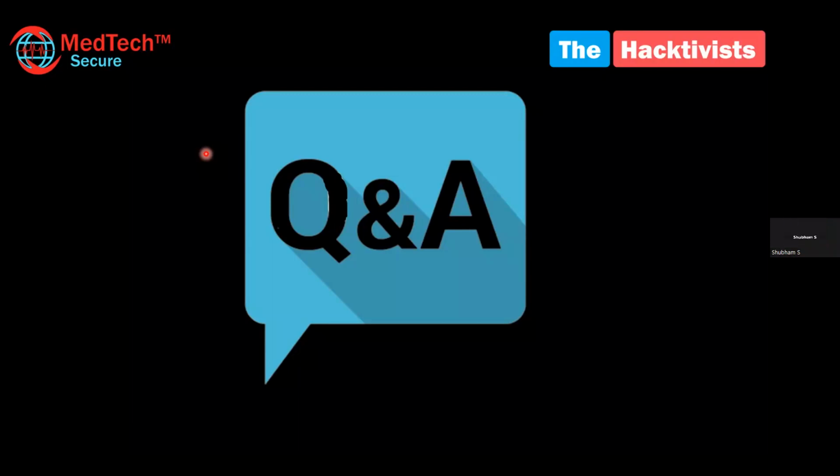What if the medical patient monitoring device, or any other device, uses a chipset the company has developed on its own? It doesn't rely on any standard microcontroller. Then I won't find anything over the internet because it's proprietary to the company. In those scenarios we can rely on open source tools like JTAGulator. If you have an understanding of what kind of chipset is being used, you can try to find out what each of those pins is used for.